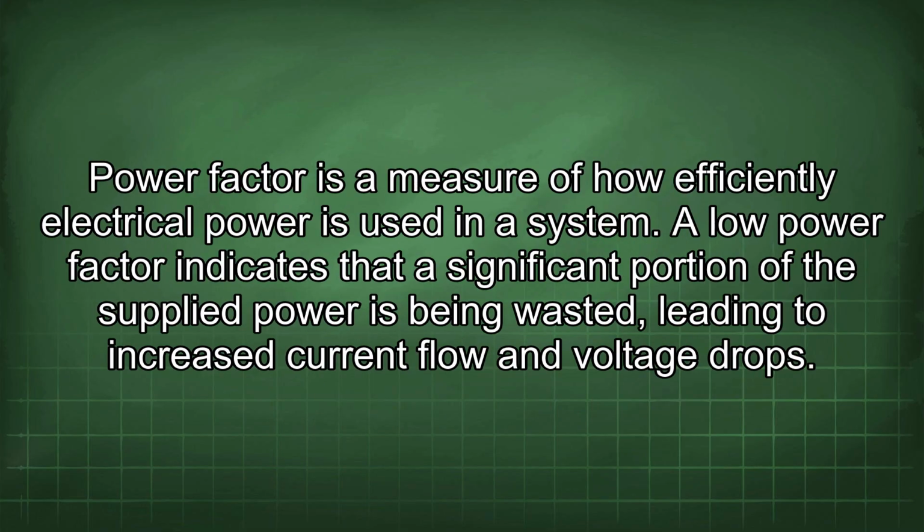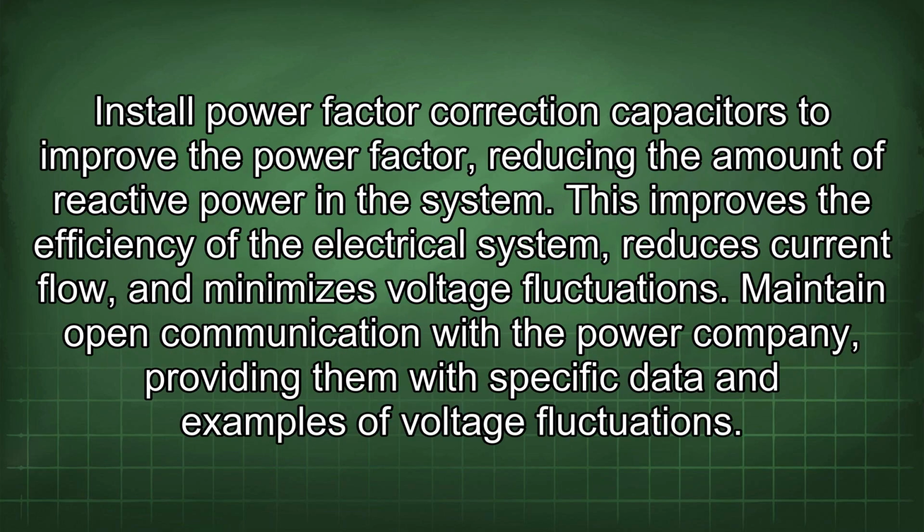Power factor is a measure of how efficiently electrical power is used in a system. A low power factor indicates that a significant portion of the supplied power is being wasted, leading to increased current flow and voltage drops. Install power factor correction capacitors to improve the power factor, reducing the amount of reactive power in the system. This improves the efficiency of the electrical system, reduces current flow, and minimizes voltage fluctuations.